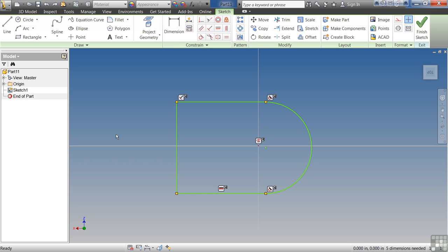Those of you who are familiar with AutoCAD may not find it intuitive to design this way. In AutoCAD, you had to draw everything out and create these precise sketches that didn't have any intelligence in them. So you could only do it one time, and then you had to go back and manually modify stuff. In Inventor, you get the design intent first by sketching out your basic shape, and then you start refining that design intent by adding geometric constraints, and then later with dimensional constraints.